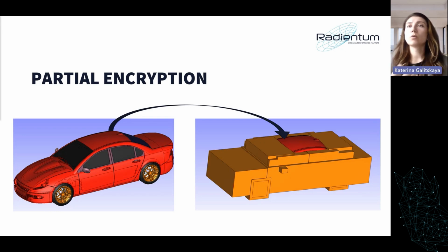If we now go again to that case in the beginning about shark fin antennas, we have some anchors on the roof. We have a separate domain for the shark fin antenna, and we apply the hybrid solver, some time domain or frequency domain for the shark fin antenna, and for example, an asymptotic solver for the whole model. And we can sweep the position of the antenna on the roof that we can see here. And it works perfectly fine.